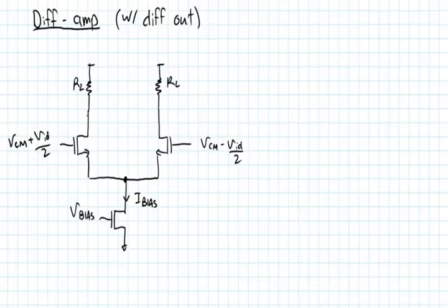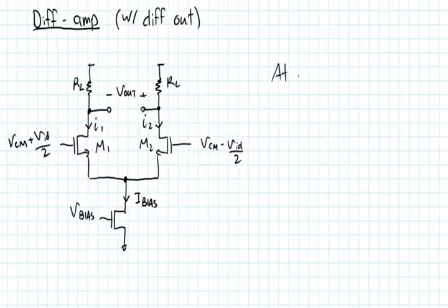And what we're going to do is take our output voltage differentially. Okay, so we're going to take our output voltage like this, and we're going to call this V out. All right, now one more note, this is M1, this is current I1, this is M2, this is current, as you may have guessed, I2. Okay, so what we can first say about this circuit is that at AC, node Vx that we're labeling here, Vx is what we consider to be a virtual ground.